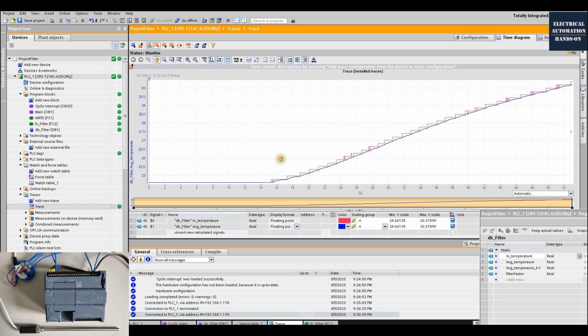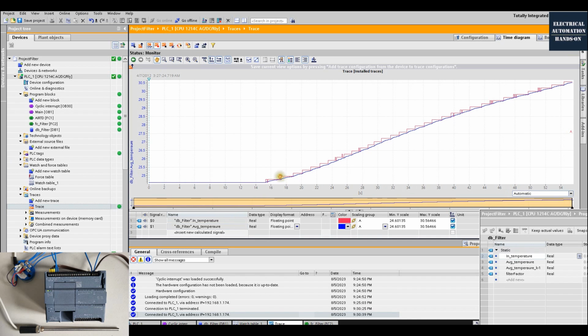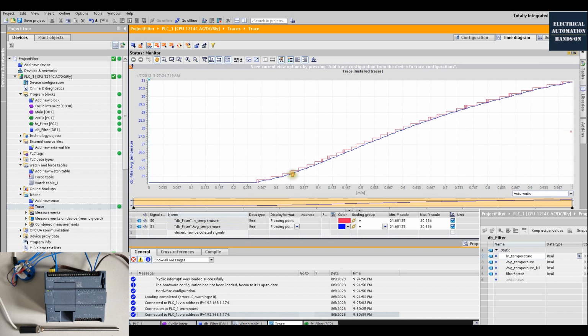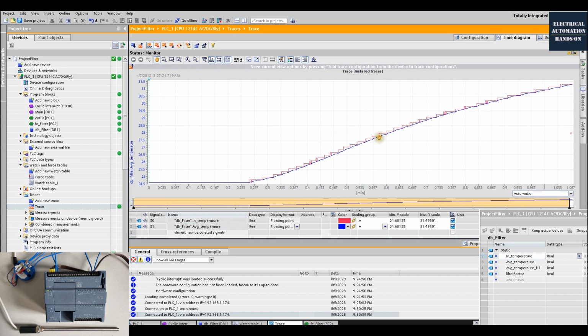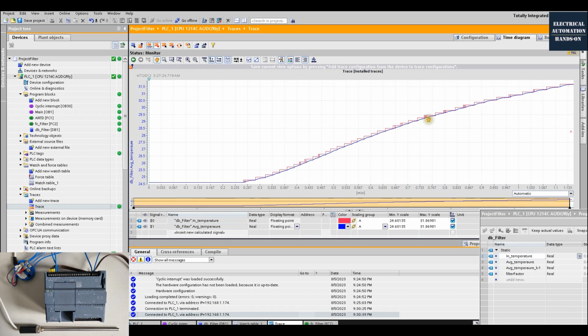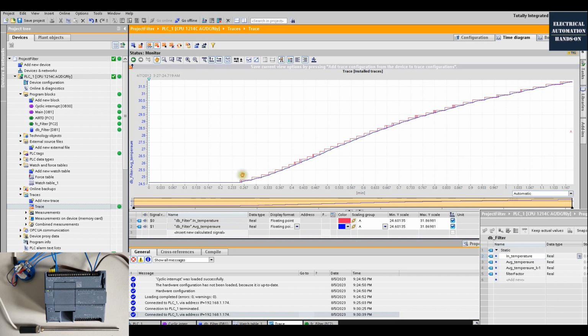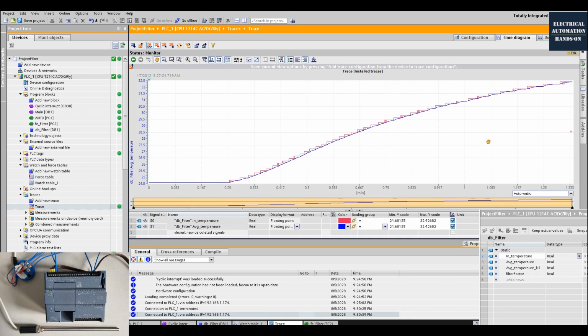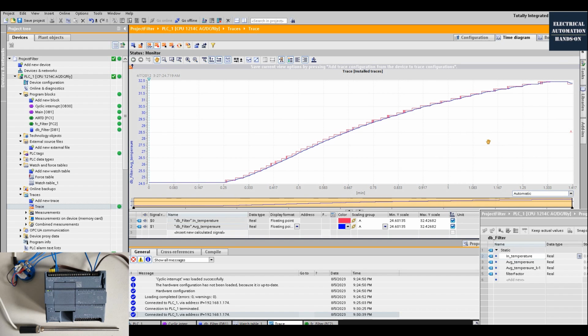As we can see here, the red is the sensor before the filter, but the blue is after the filter. We will see the significant difference, right? So it has the noise come with this temperature sensor signal, and this blue is super smooth, right? So it's increasing. Now I will drop it into cold water, and we will see the temperature will decrease.